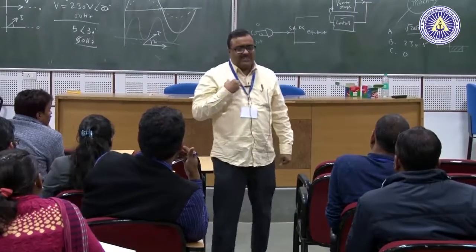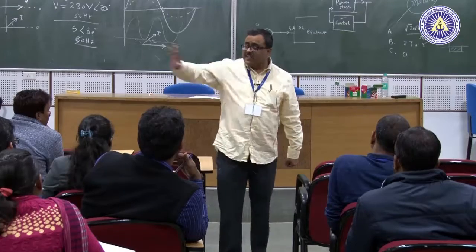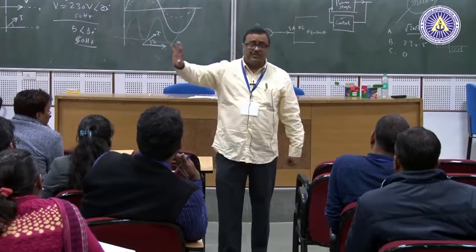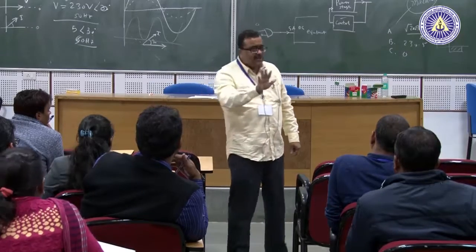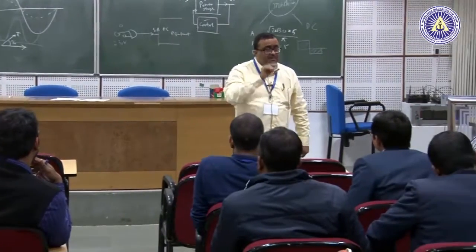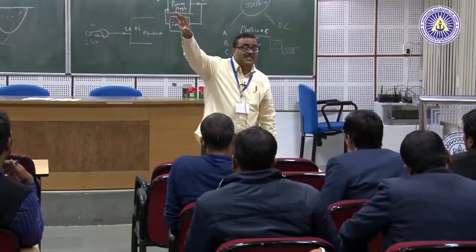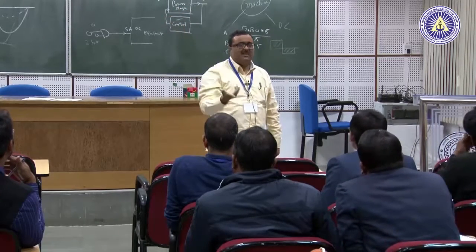I have tested myself, I cannot hear more than 5K. Dogs can hear 10K or 15K or 20K, but my ear cannot hear more than 5. So, if I put the harmonics in the 100 kilohertz range, then I cannot hear, my fan will not make any sound. That is precisely what is done.